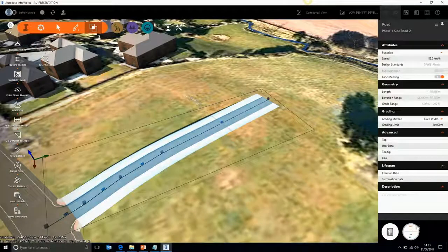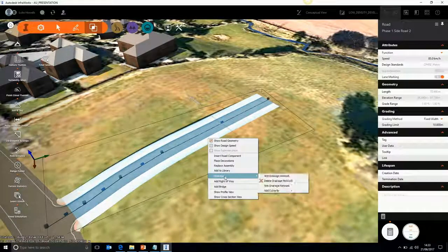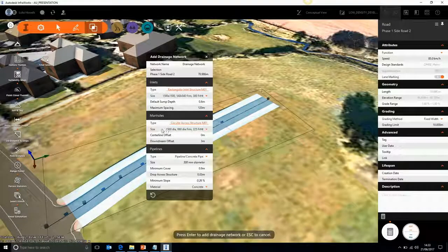I can do a cut and fill calculation. So I can do the materials quantities, I can then kick out and actually then give myself a cut and fill report at this stage. But one of the nicest features, and especially on the early design stages when we're looking at developing this for a housing layout, is I can just right-hand click and immediately add a drainage network to it, which is then exportable into Civils 3D, which these guys can actually talk you through a little later.